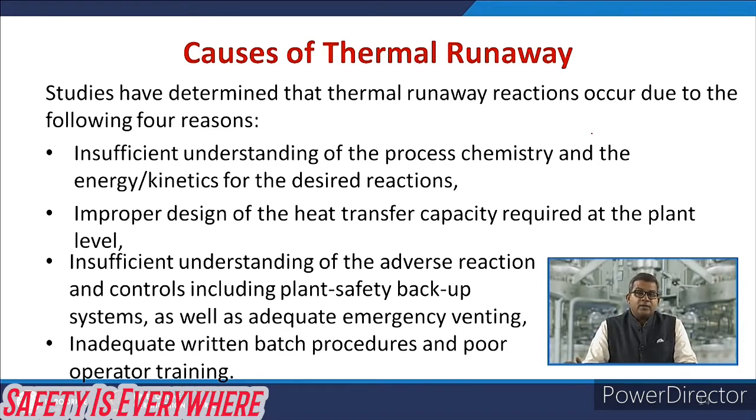Now this is again very important, because you know theoretically how much heat is being generated in that particular process. So if your design is below the required heat capacity, then definitely you are approaching the thermal runaway aspect. Sometimes there is insufficient understanding of the adverse reaction and control, including the plant safety backup system as well as the adequate emergency venting. Again, it's a very crucial aspect attributed to the design of the reactor.